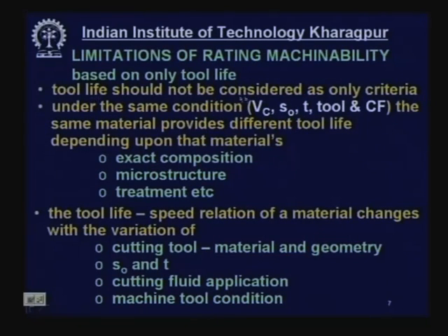Tool life should not be considered as the only criterion. There are many other criteria like power, energy, cutting force, tool life and surface finish, dimensional accuracy, cutting temperature and what not. All those things should also be taken into account under the same condition, that is under the same condition of machining, of cutting velocity, feed, depth of cut, cutting tool material and geometry and cutting fluid. The same material provides different tool life depending upon those conditions.